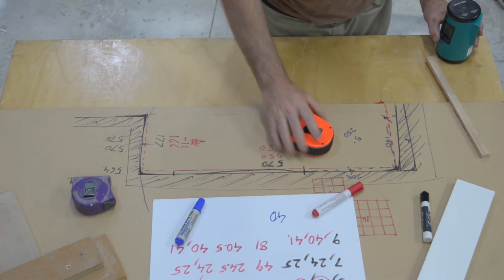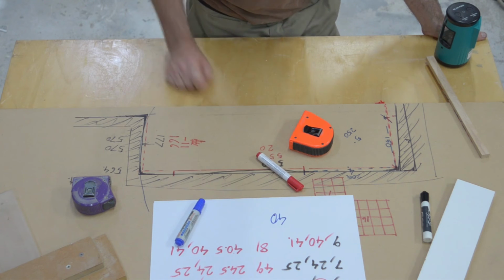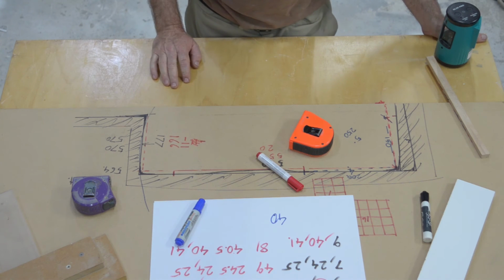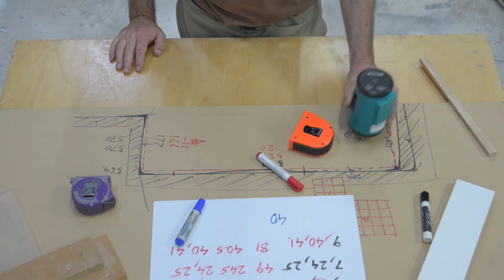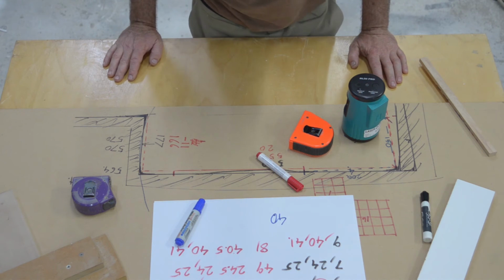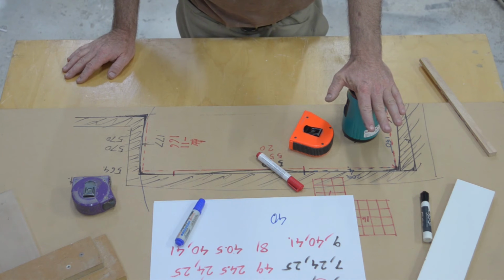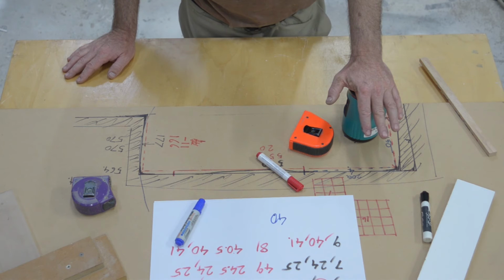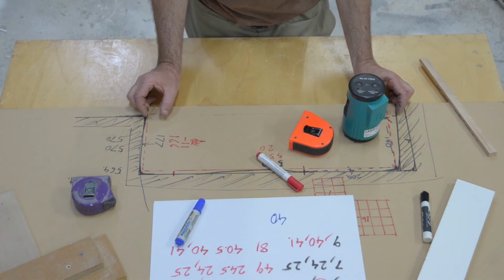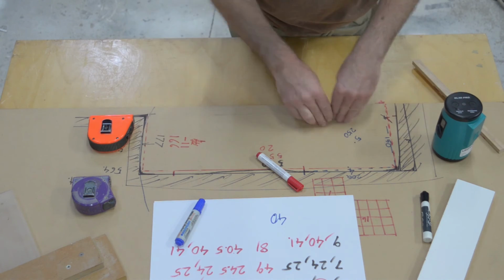Everyone has got a tape measure if they're doing any work. Something to write with, something to write on, and a brain. So these methods that I've shown here are methods for handling with limited resources. If you've got the ability to get hold of a laser, buy one, own one, or borrow one, or rent one for that matter. I don't know whether they're rentable. But in any case, these sorts of pieces of equipment can save you a lot of time and really bump up the precision. And of course, the easiest way out is to build in a lot of tolerance into your design, like having an infill panel either side that will give you 20 or 30mm space, or in depth, make sure the cabinet's much shallower.